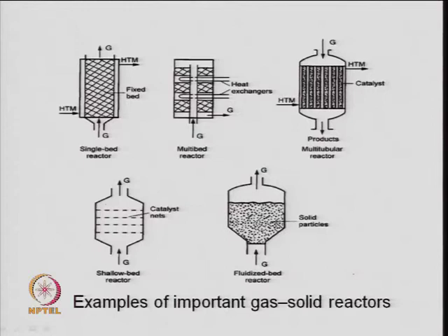Yesterday I was talking about the different types of systems and heat transfer when the reaction is exothermic or endothermic. So, we put in multi-tubular or multi-bed reactors. This is a multi-tubular reactor here, and this is a single bed reactor. Again, the type can be for heat transfer. You can see a jacket outside, with some heat transfer fluid passing through the jacket. It is not agitated, but it is jacketed. So, it is a kind of shell and tube type heat exchanger. Continuously the cooling can be done here when heat is generated throughout the system.